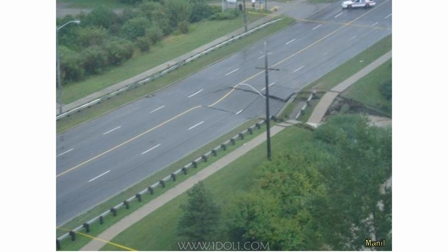It carries the sediment with it, and it goes through this process where if the fine soil gets washed out, then it makes the voids larger, then the water velocity can increase, and there's further energy going through there that can carry larger particle sizes. And it's kind of a progressive thing where eventually you've got water seeping at a higher velocity, which carries more soil, and it can cause a structural collapse, which is what happened here.